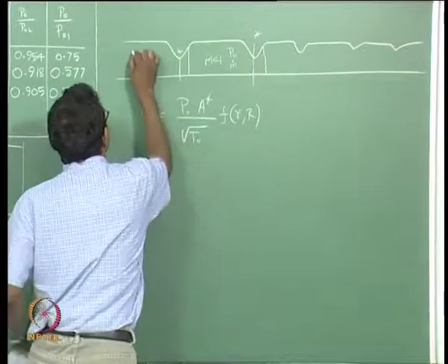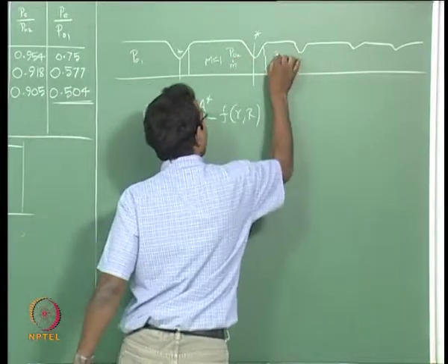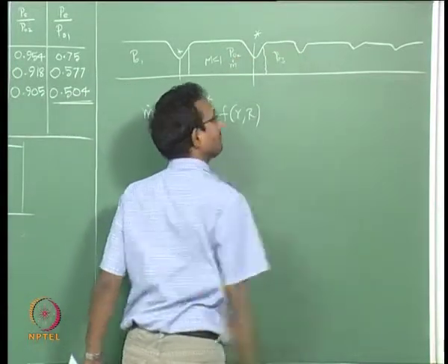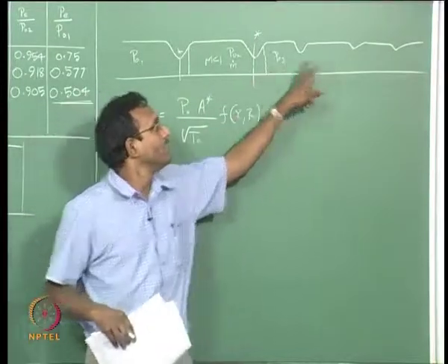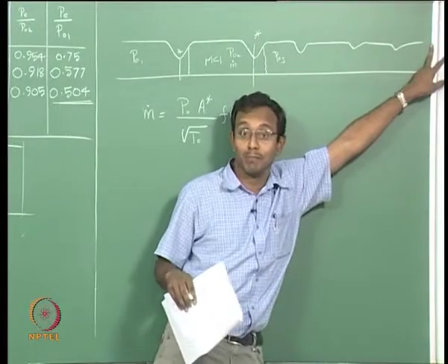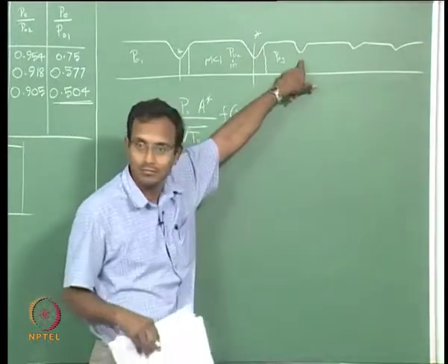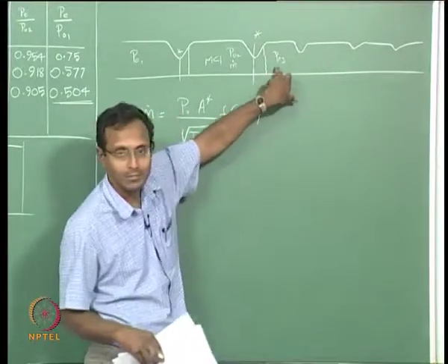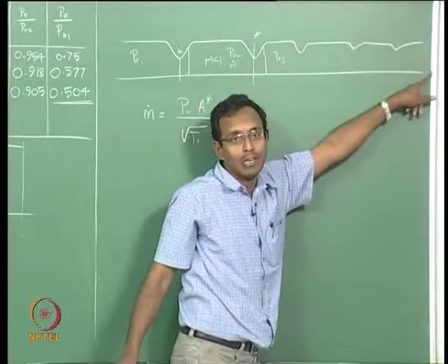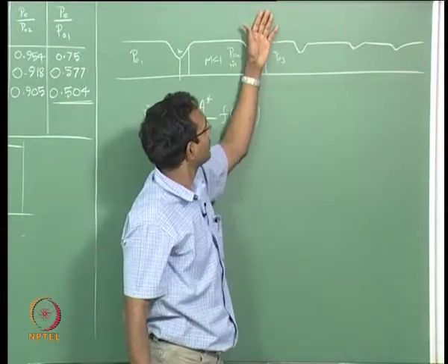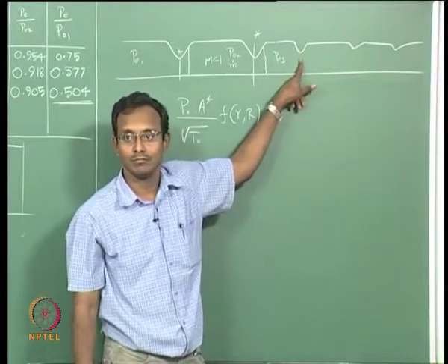Okay, we will make it numbered P01, P02. Now I have a P03. That is a possibility. Okay. Now if I decrease my pressure further downstream, P back really low, then I can still make it choked here. For this P naught, I just look at this problem from this point on downstream. If I make my PB low enough for this particular P naught 3, then this condition may get choked, right.